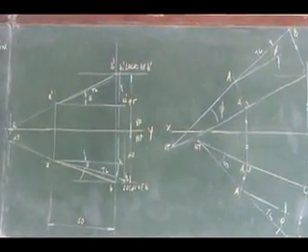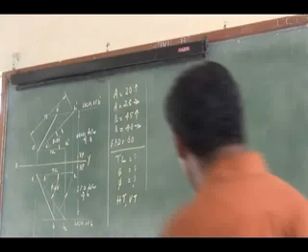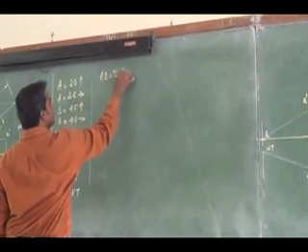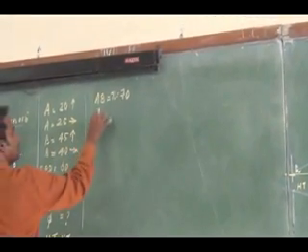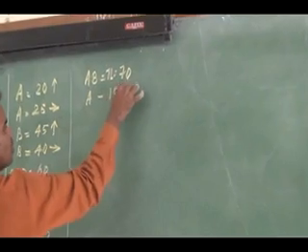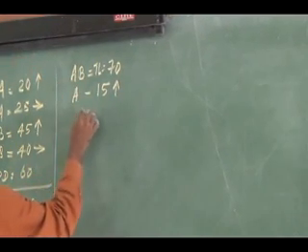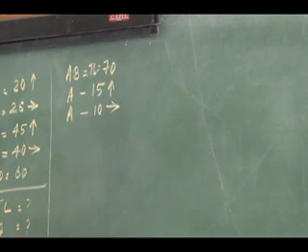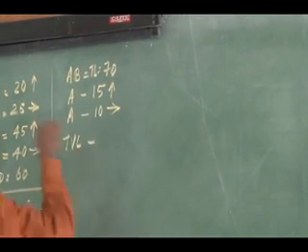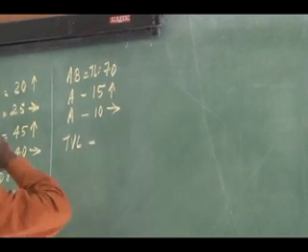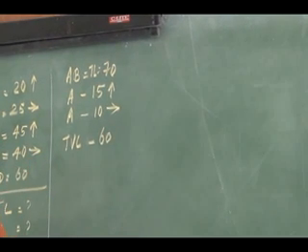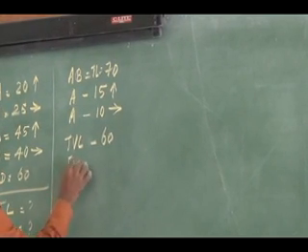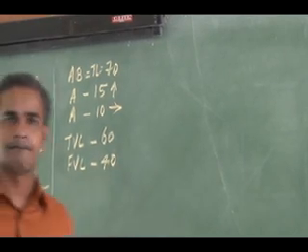Take the problem. A line AB of length, this is nothing but my true length, is 70 mm, has its end A 15 mm above HP and 10 mm in front of VP. Top view length measures 60 mm. Front view length, 40 mm.